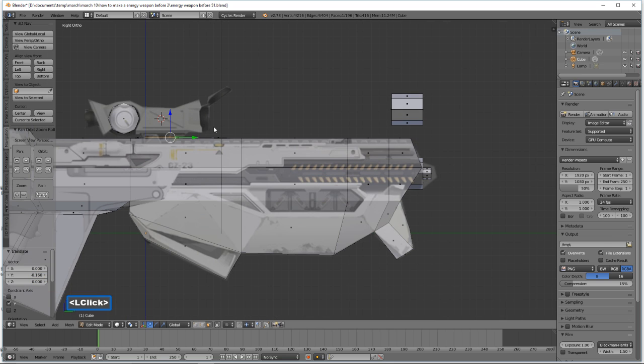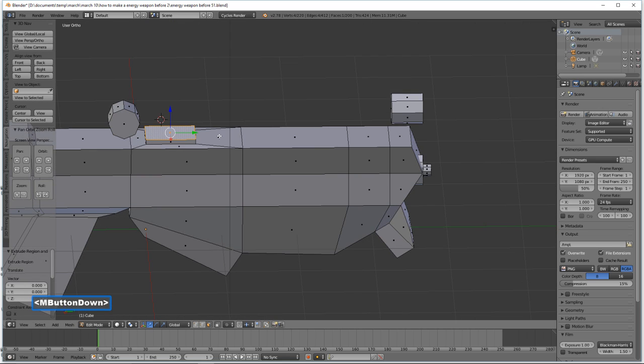Okay, we'll click here to go back to right view. We'll press E to extrude on the Z axis. We'll bring this up some. See how it's wobbling? So I'm going to press Z again so it's not wobbling. Like that. And just like we moved here, what we can do is press A to deselect.